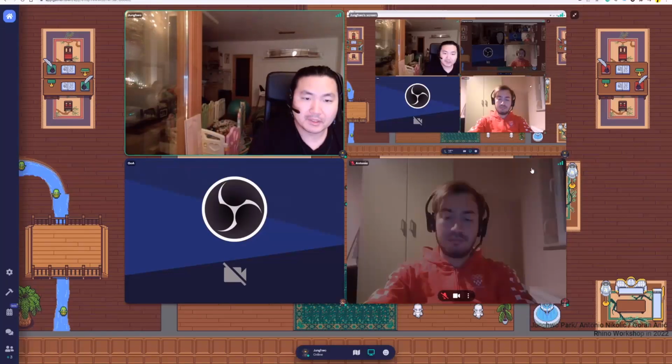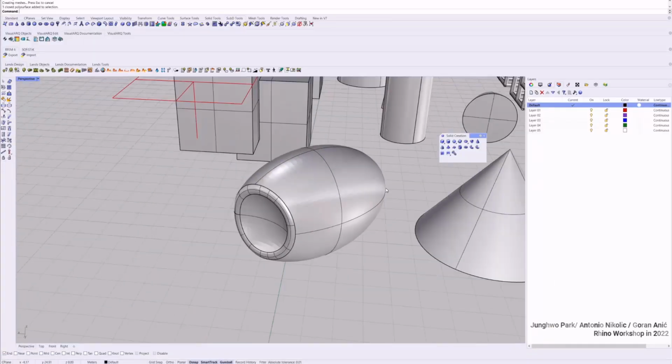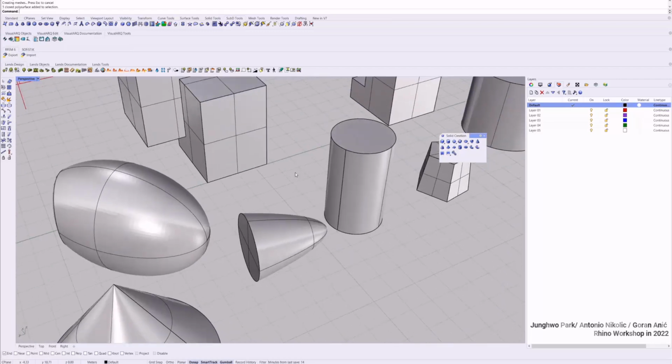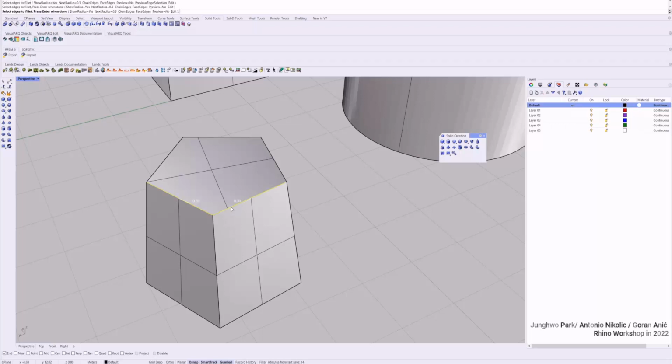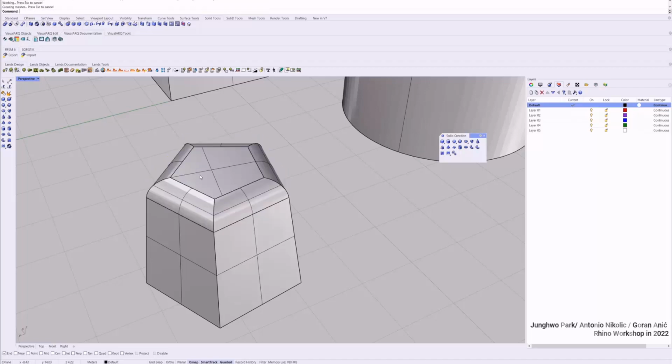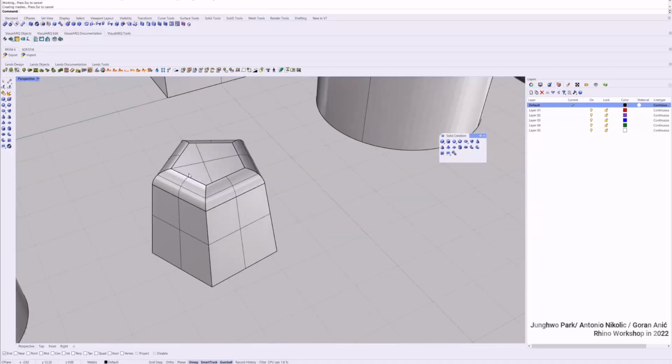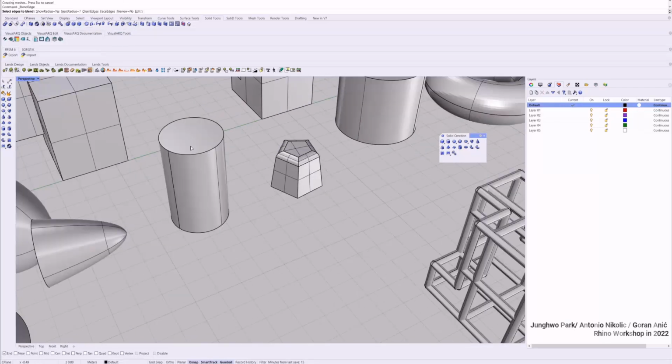Are you guys with me? Yep. Okay. Yeah, we're following. So let's try one more time. Solid, like fillet edge. So when I go to solid, and I click on fillet edge, this time I'm going to select all of this. Hit enter, and you can fillet the edge. There is also, with the mouse right button, blend edge. We can try.